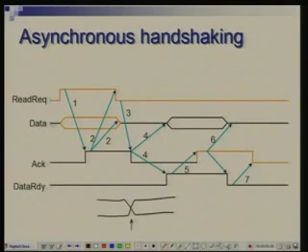There is neither a low impedance path to ground or 0 level, nor a low impedance path to power supply or 1 level. Symbolically this is shown as an intermediate level. So the data bus up to this point was floating, in high impedance state. Here some bits go to 1, some bits go to 0, and this state continues. At this point the address is removed from the data bus by the device which was driving it, and the bus floats again.